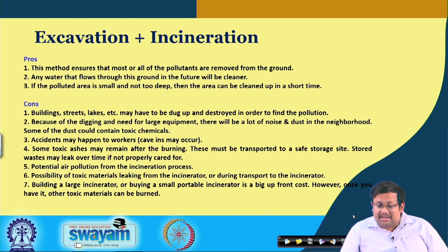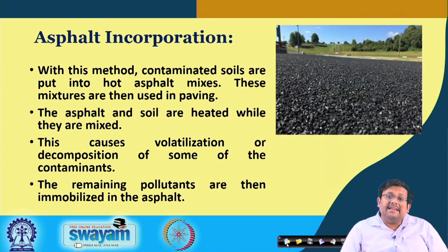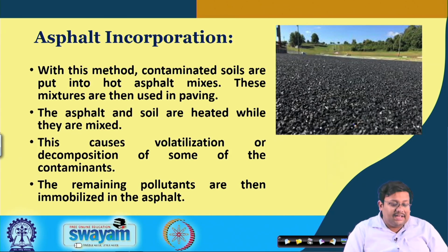So, we have finished this excavation and incineration, and the next method of ex situ decontamination is asphalt incorporation. Now, with this method, contaminated soils are put into hot asphalt mixes, and these mixtures are used basically in paving, as you can see in this picture. The asphalt and the soil are heated while they are mixed, and this causes volatilization or decomposition of some of the contaminants, and the remaining pollutants are then immobilized